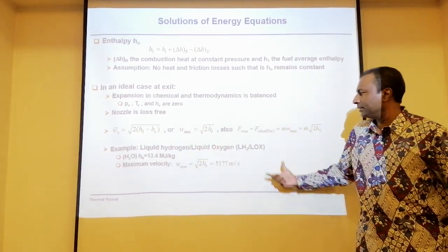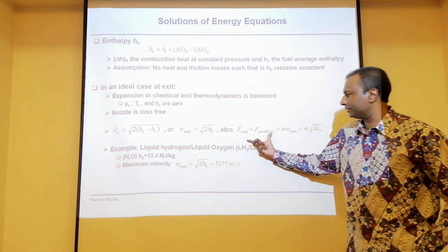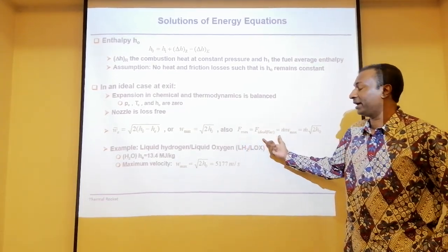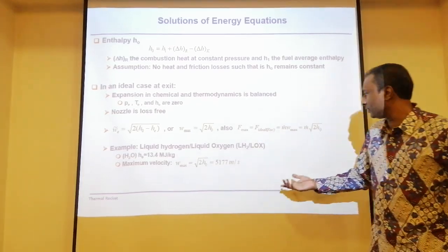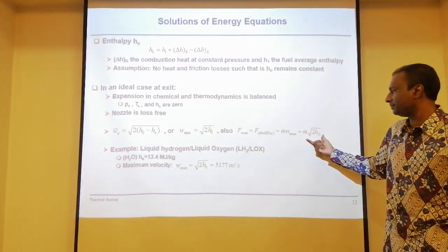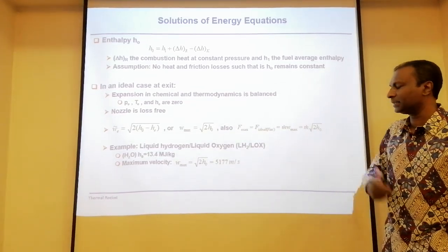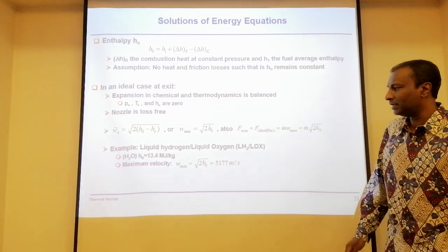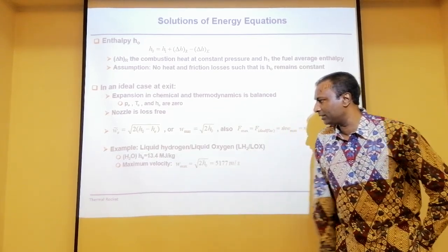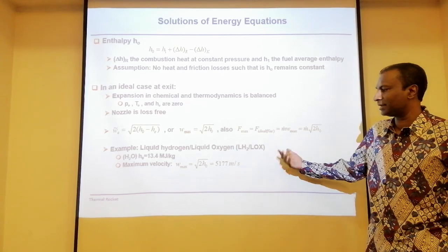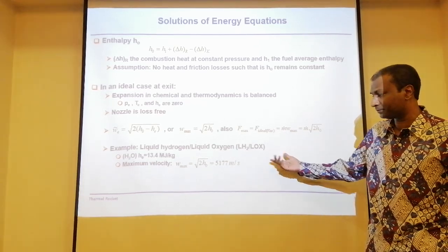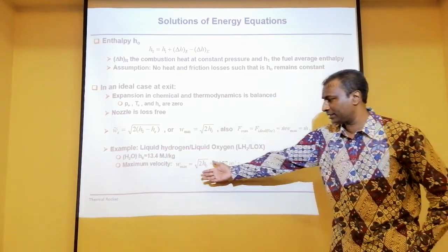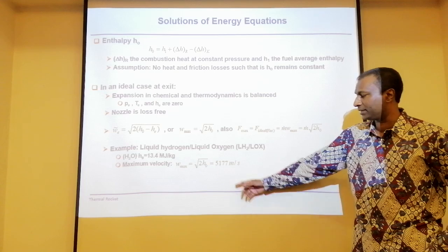Alright. Now for the thrust, if you look at it, F max or F ideal is in vacuum. So therefore, this formulation can be used. It is basically your m dot with respect to your enthalpy as well. So for typical liquid hydrogen and liquid oxygen, let us calculate the exact enthalpy. And when we have an exact enthalpy, your W max can be calculated.